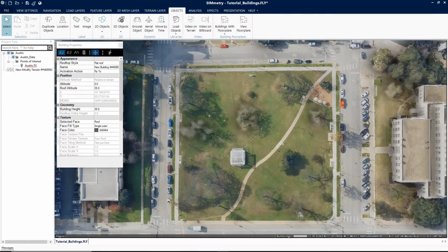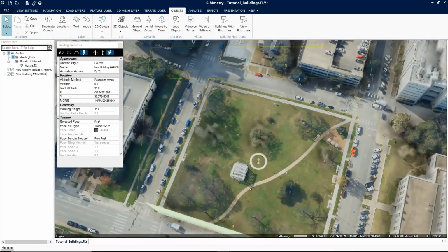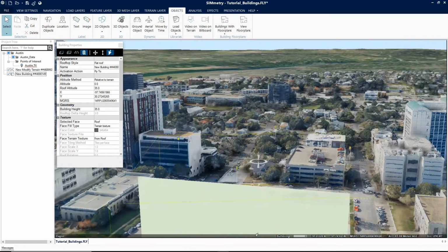To create a new building, in the 3D window, click the mouse on the required location to add the first point of the roof. Click again to add additional points of the roof's polygon until you have marked the entire shape. You must place at least 3 points to define the roof. Right-click to finish the roof polygon. Use the mouse pointer to drag the base polygon, which is in green, to its base on the imagery, and left-click to finish the operation.